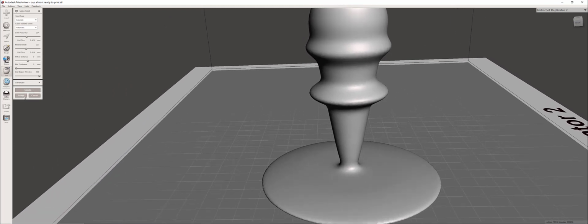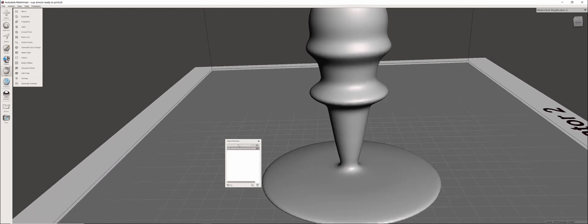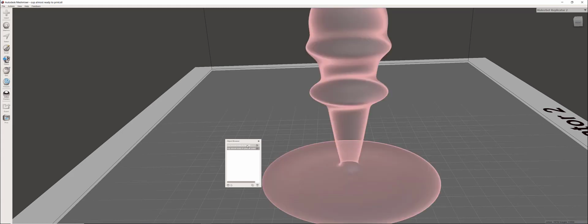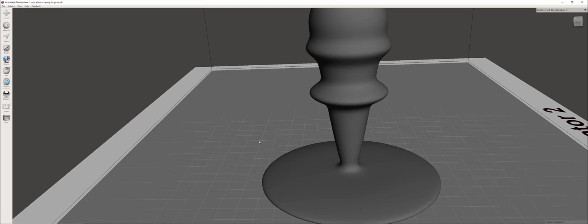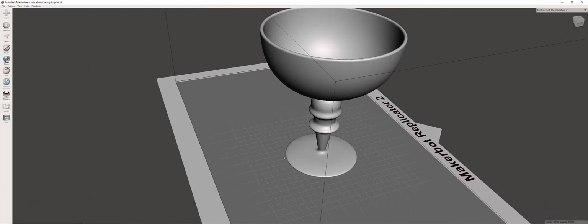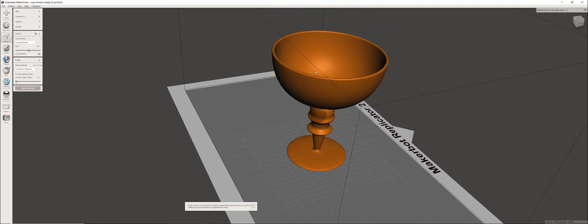Yeah, accept that result. So here it's showing me the old part and the new part. So we're going to delete the old part. We don't need that. We're going to work with this one. And on your keyboard, guys, put this on your paper that you have already stuck to the wall. I know you already did it. Put the name Mesh Measure Commands, and you're going to press Control, maintain the Control on your keyboard, and then press A. Okay, so it's going to be yellow.